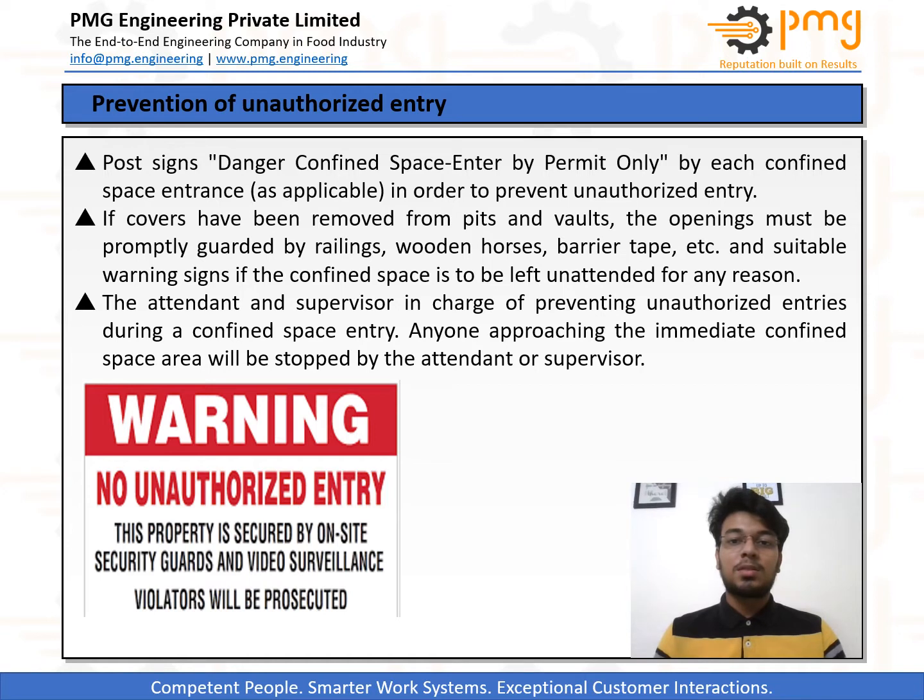By timely actions, I mean they need to put up easily understandable signboards that say danger or stay away or anything similar that will do the job. The entrance to the confined space should always be closed. In case a cover is not available, the entrance should be secured with barricades or guards. If the attendant or the supervisor sees anyone approaching the area, they should intercept them immediately and remove them from the site.